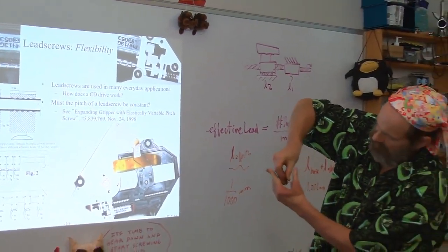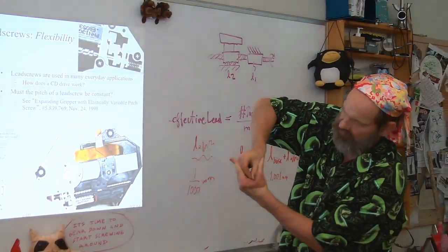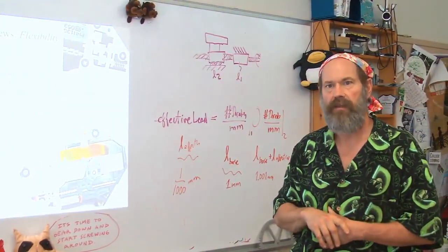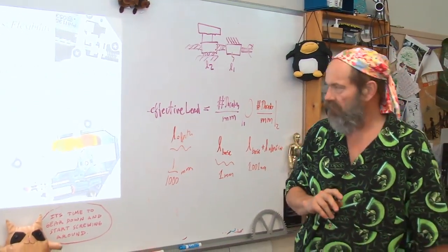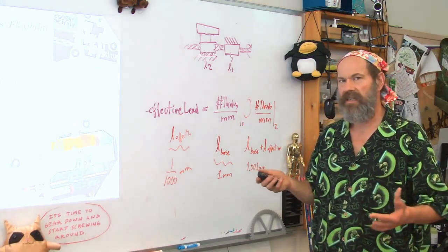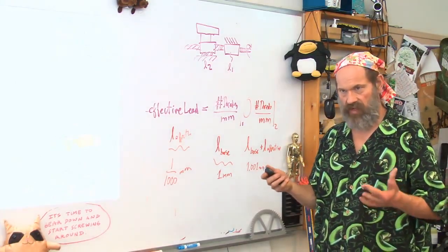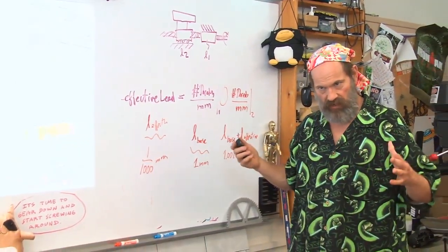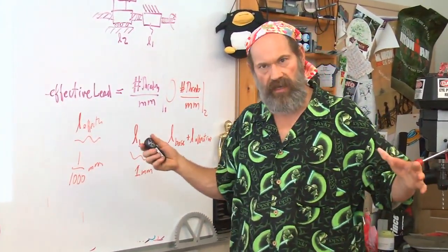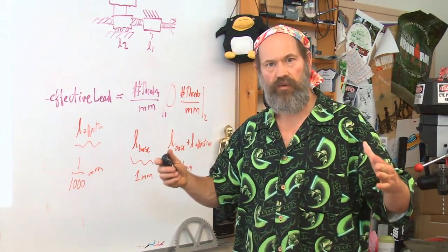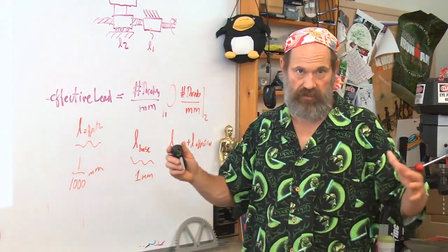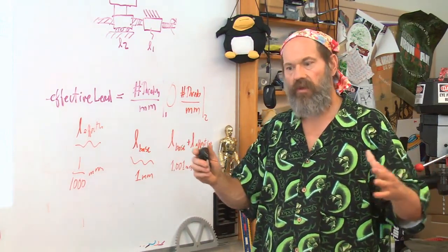The trapezoid preloaded under the receiving trapezoid, just like the timing belt teeth we talked about yesterday. So never be too limited in how you think about achieving the functional requirement of preload. Some sort of spring somewhere in the structural loop is stretched somehow and held in order to take out any gaps that you may have, regardless of how the system may move.